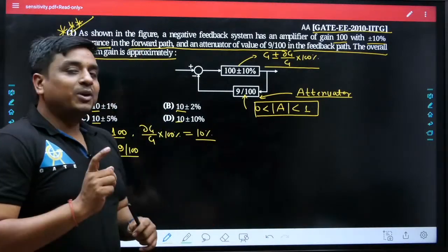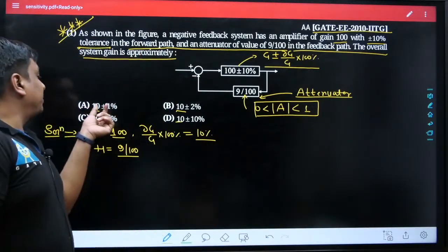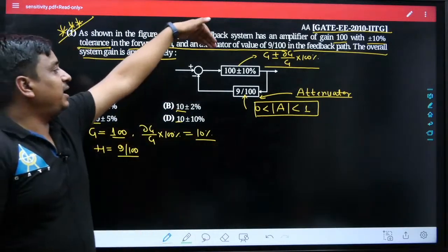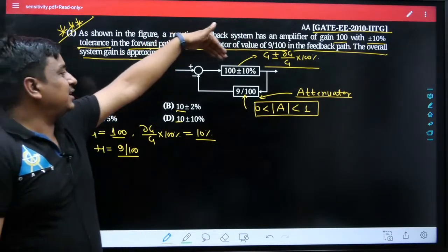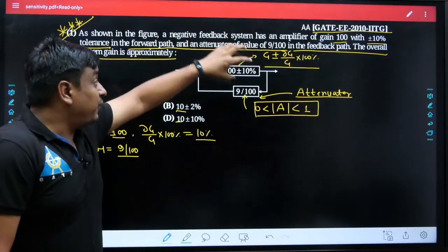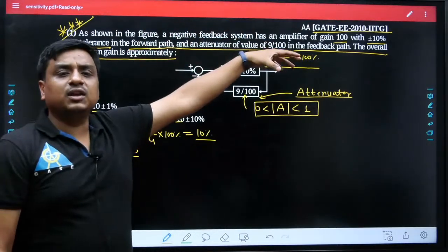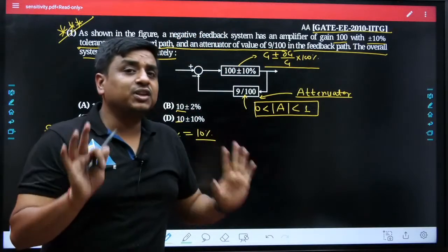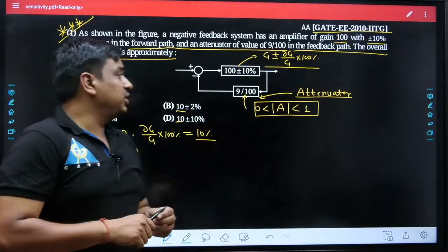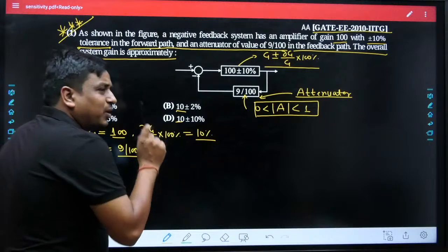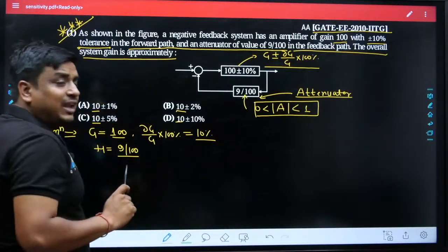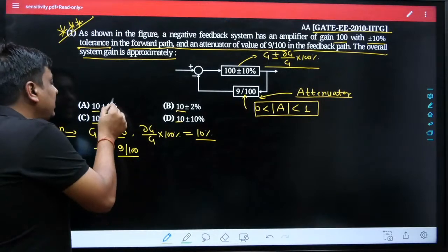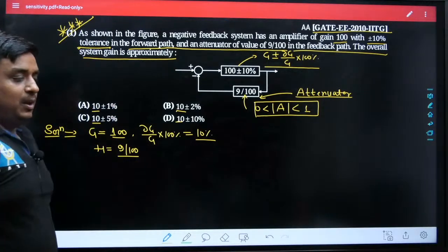Yes. So nobody should have any sort of confusion how this percentage of 1%, 5%, 2% or 10% has come into the picture. Keep in mind, if G is supposed to change by a certain percent of G, the effect of G would also go over to the effect on T. Could you understand what I am saying? So now the concept goes this way. First you will calculate the perfect value of T, and secondly you would calculate the percentage change over the T. Here goes your perfect value of T and here comes your percentage change in T.